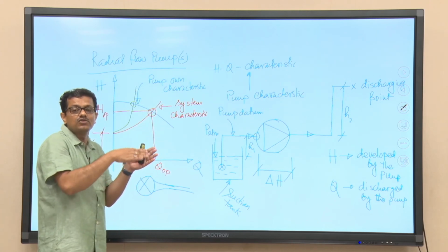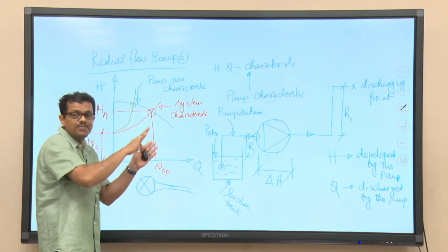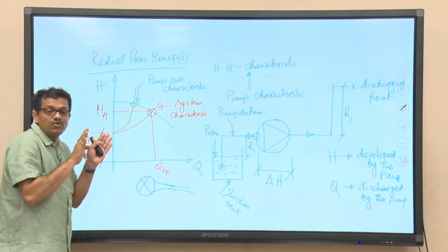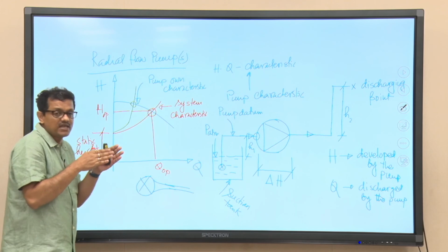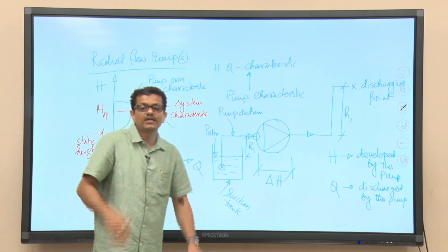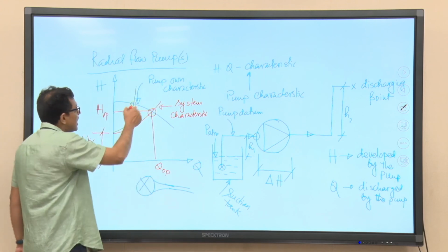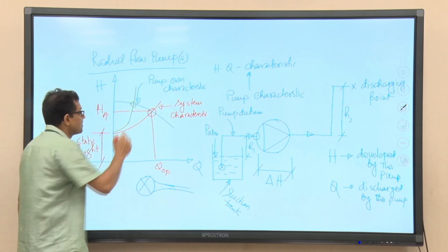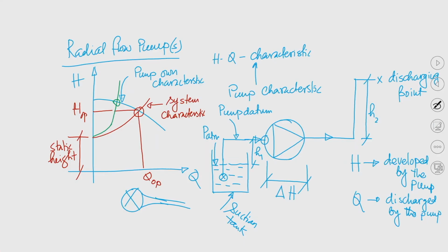The pump designer, based on those input parameters, has designed the pump, and this is the H-Q curve. Now, as I said, the system resistance calculated initially is not correct. So, basically it was calculated by mistake. So, if this is the actual or corrected system resistance, you can understand this will be the operating point. So, our expectation is that we will get this amount of flow rate, instead we will get this amount of flow rate. So, basically this is Q operating new, and this is H operating new.